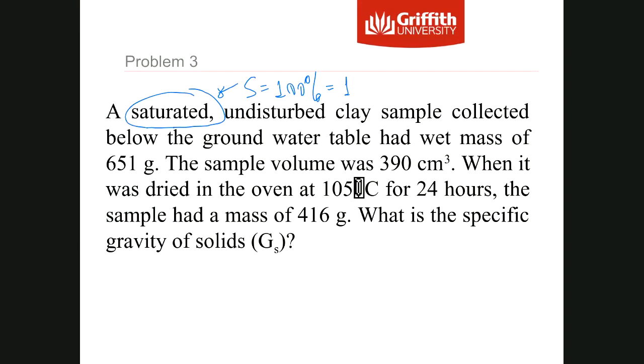I don't say that this soil has degree of saturation 100%, but I say soil is saturated, which means you should know this one. This is very common in quizzes, in all the questions that I'm going to ask you. I'm not going to tell you the degree of saturation, but I will tell you that the soil is saturated. In this case, degree of saturation is 1.